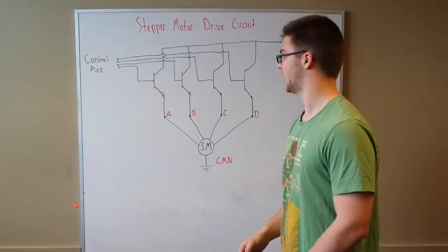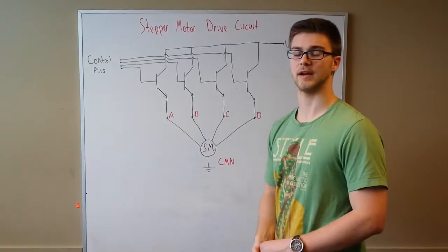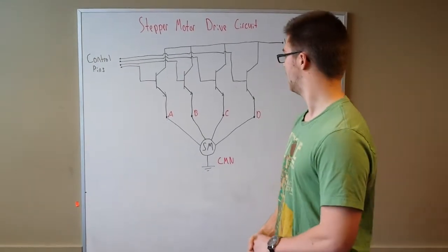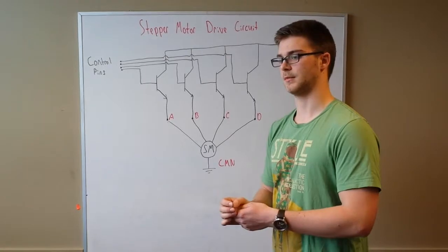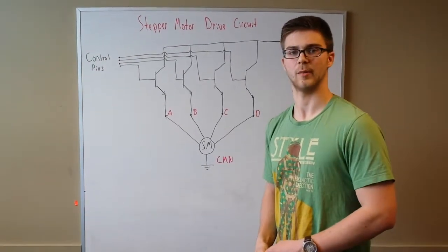We decided to use a stepper motor because I found it very easy to write a driver for in software, and its ability to rotate a specific amount and then maintain a torque at that location was very appropriate for our application.